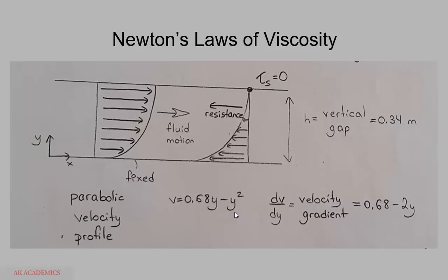And that corresponds to the fact that when you come to the top here, we have said that at the top here, the velocity gradient is low. And when the velocity gradient is low, the resistance to the flow of fluid is very low. So at the very top here, this is where we have the lowest resistance, and that means our shear stress at that particular point is going to be equal to 0. Okay, it's approximately 0. So this means we're on the right track with our calculation.